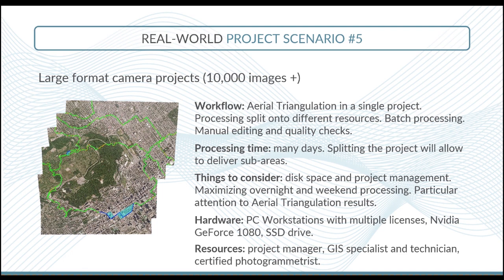That will be easier for you to manage the accuracy of your block. Maybe it's going to take some time to measure all your ground control points, but you won't have to worry about having different blocks and ensuring that they fit with each other. So that's what I would recommend: doing only one project for the aerial triangulation.